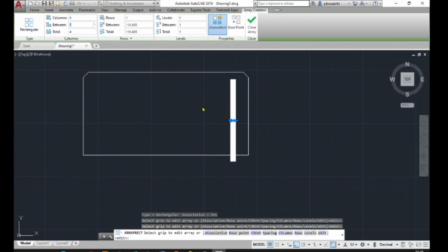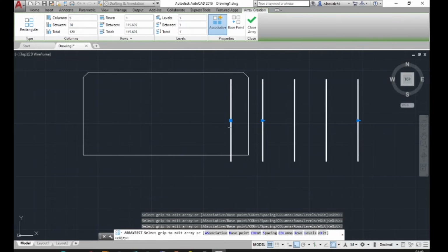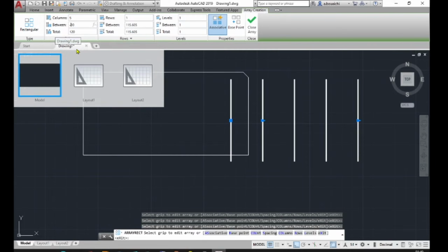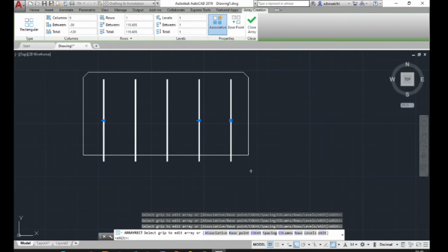So this 5 bus bar must be divided into the solar cells with 156 length. We can make, for example, 30. Press enter. To make the array in the left side, we can make the value as minus value. We added minus and press enter.